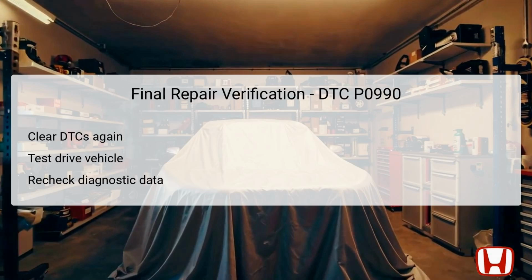Once all necessary repairs or replacements have been made, the final verification step is essential to ensure that the DTC P0990 has been resolved effectively. Begin by clearing any stored DTCs once again using the HDS, emptying the system of any prior errors. Following this, conduct a test drive to observe the vehicle's performance under various conditions.